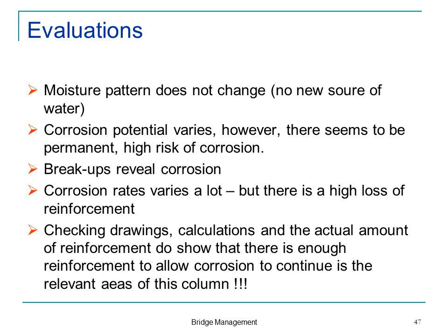But then, when you look closer, you realize that when you cast a foundation, you have some reinforcement bars that stick up, and then you come with your reinforcement cage and lower it on top of that. At this cross section, there were not 25 bars, there were 50 bars of 32 millimeter. I think we could lose 90% of the reinforcement without any problem. It looked awful, but it was not a problem.